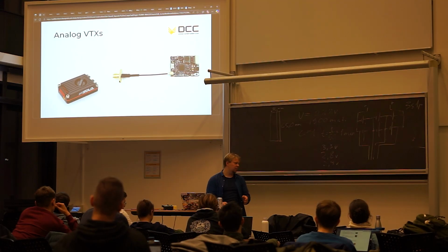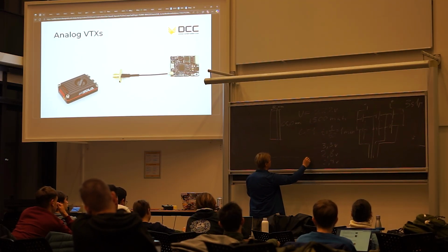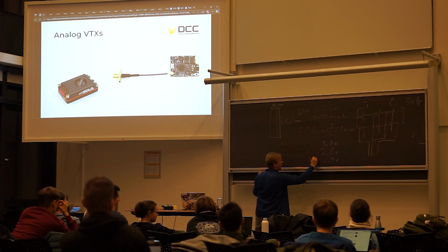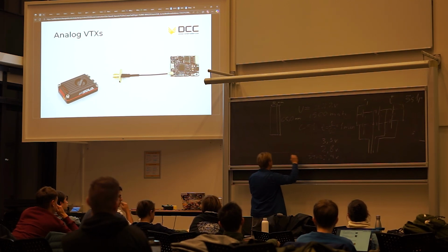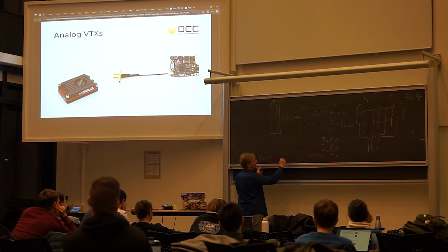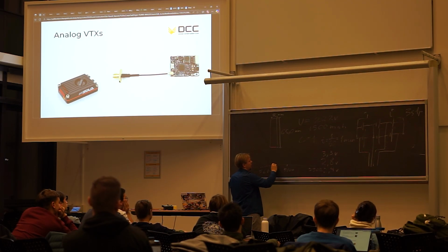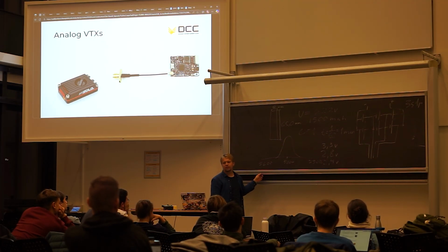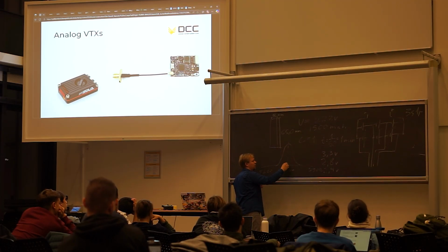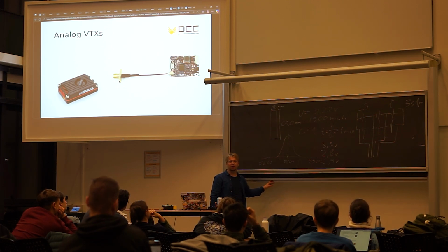It's analog. The transmission in the spectrum, let's say you have a spectrum, frequency, I don't know, 5,900, from like 5,600. Let's say you pick a channel that is supposed to be perfectly 5800. The VTX is going to blast it like a nice bell curve somewhere around the middle. Should be 5800. But if there's someone close, it is all analog, so it will overlap. You will see the other people's videos and stuff like that.